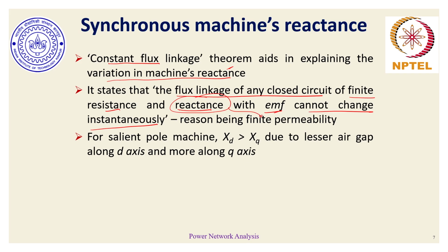And for our discussion, to apply this for salient pole machines, we'll assume that XD is the dominant reactance. So we'll correspondingly ignore the value of XQ and look at it from the perspective of how XD has its variation. For salient pole machine, it is all about XD, whereas for cylindrical pole machine, it is all about the synchronous reactance XS.